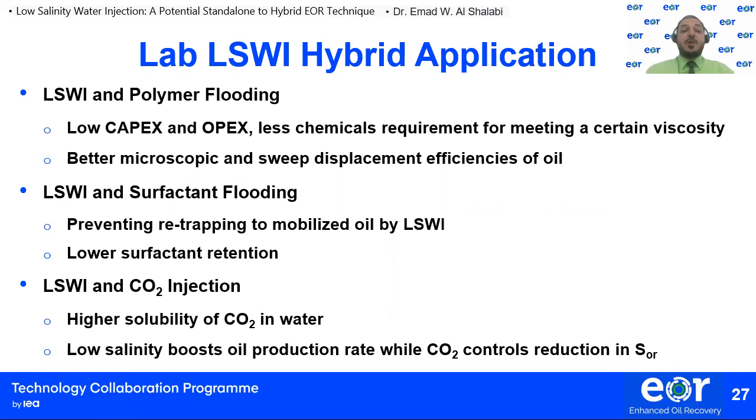Here I'm showing some of those hybrid applications of low salinity that have been proven at the lab scale. First, low salinity water injection and polymer flooding. Once you reduce the salinity of the water, you need less chemicals, less polymer, to meet your target viscosity. That reflects positively on your CAPEX and OPEX requirements, and you also have better microscopic and volumetric sweep efficiencies.